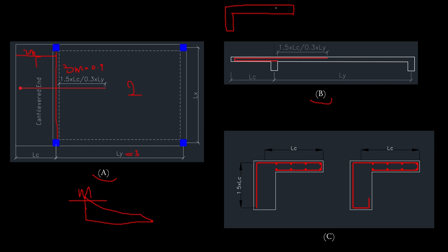So in that kind of situation, the reinforcement, which is the top reinforcement, is going to be extended into the supporting beam, because this containment needs to be satisfied. And the reason why we are returning or extending that reinforcement is that we want to transfer the forces on the reinforcement into the support, because that is the condition of design, of analysis.